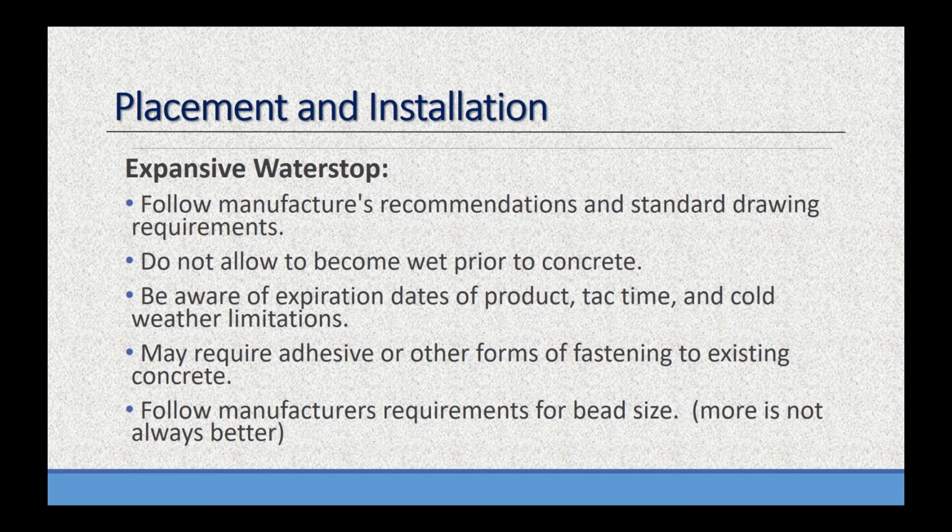Obviously, don't let the hydrophilic water stop become wet before the concrete is placed. It's going to expand and not do what it's designed to do. Make sure you're aware of the expiration dates. Some of these hydrophilic water stops expire. Make sure you're familiar with the set time and the cold weather limitations. Some have more extreme cold weather limitations than others. It's the knowledge of the product. Conversely, you take the knowledge of your product and that becomes your inspection item.